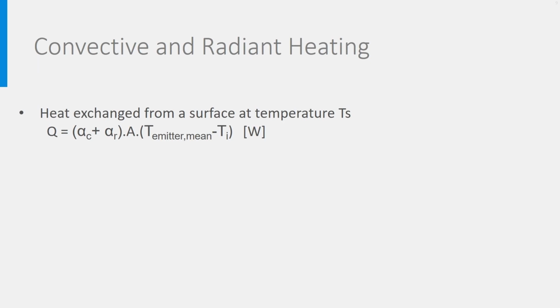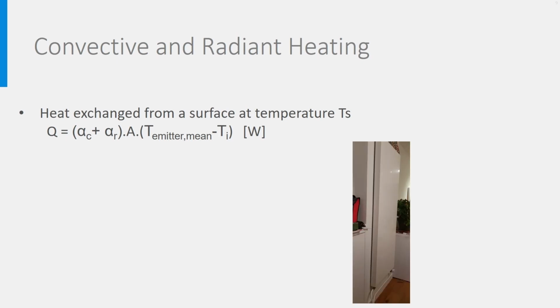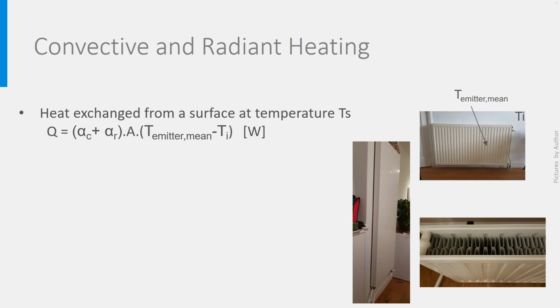In some cases, the emitter has just one flat plate, like this one. In other cases, the plate is corrugated, like on the radiator above and on this picture. Additional plates are added, increasing this way the effective heat transfer surface for convection. So, in general, we can rewrite the heat transfer equation like that, taking into account the outer radiative surface A and the surface for convection Ac. The radiative share can then be calculated easily.